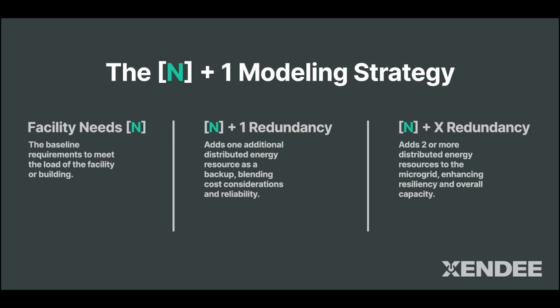Traditional redundancy follows the N plus X strategy, where N is the original number of equipment or capacity, and X is the number of backups. In this example, we specifically use an N plus 1 strategy, but with additional considerations for the smart dispatch of the technologies. This can mitigate capacity oversizing, and cheaper solutions may be possible.